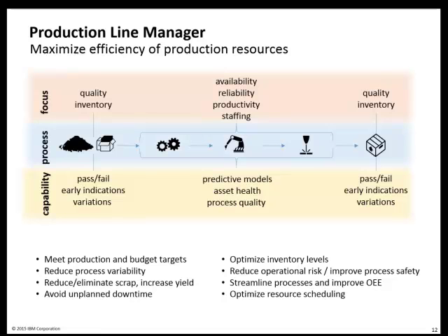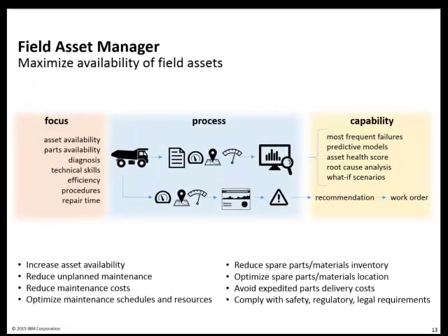Another aspect or application of predictive analytics, very similar to the maintenance organization, but this time associated with the field asset. Here they've got the responsibility for addressing maintenance concerns over assets that might be widely and geographically distributed. And here, again, same process, looking at the key assets, developing the predictive model for that asset so that we can anticipate what the most frequent failures would be, develop an asset health score, root cause analysis, and then once that asset is in operation, getting real-time data for that, comparing that against our asset model, and in the event of an alert, issuing a recommendation and work order